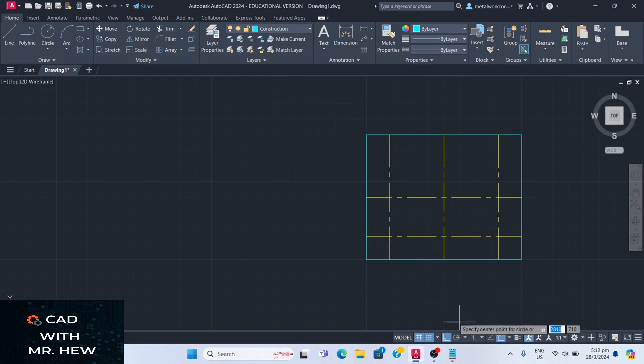all right, I have to turn off object snap, which is this icon for it to come here, right? Now you move the cursor until you see that red X and you see the word intersection, and you know that the cursor is aligned to the intersection of those center lines, all right? All right, so we're gonna click it. It's asking us for the center point. We click it.